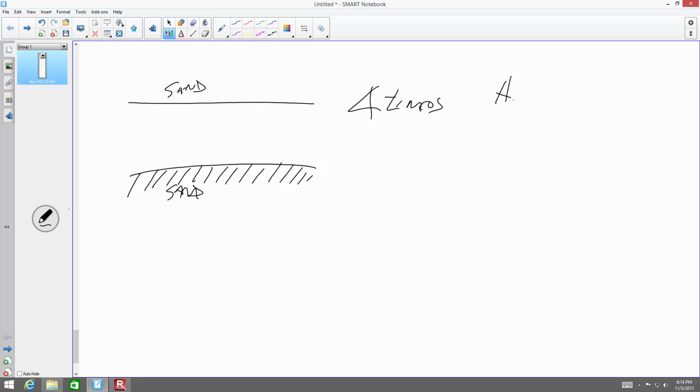Because it's HDR squared, right? HDR squared is in the equation. If it's double drainage, HDR equals H over 2. If it's single drainage, HDR equals H. So 2 squared is 4. So it changes by 4.